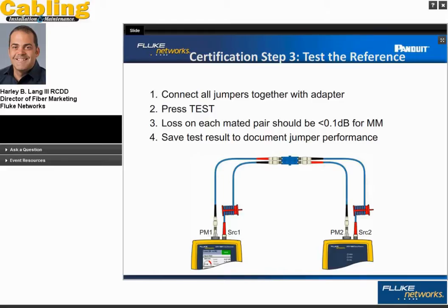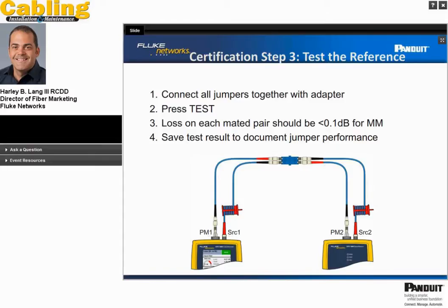We also have many knowledge-based articles on the Fluke Networks website that show you how to test cords. You can test the cords you have to make sure that even good quality test reference cords haven't degraded over time. Having good cords also reduces some concerns people have about setting a reference, where you have to use a known good cord. So those cords can be verified in the field.